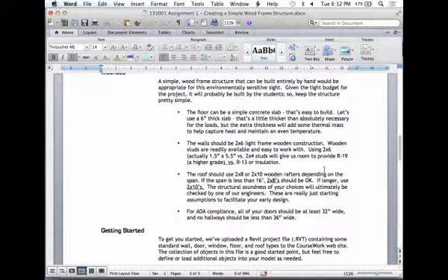Okay. Last thing we need to worry about, just for ADA compliance, any doorway has to be at least 32 inches wide, so we can sort of wheel a chair through there. And if there's any hallways, there probably shouldn't be that many hallways, but anything that looks like a hallway should be at least 36 inches wide. There's plenty of room to kind of pass through. Okay, so that's kind of the general idea of the construction technique.